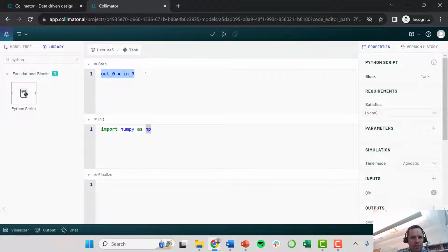I'm going to go ahead and delete this block, and here is where I'm going to start coding in my basic model. I'm going to start with this core material balance, which is a differential equation, and this is qin minus qout. So dV/dt equals qin minus qout. However, remember, qout is not something that's going to be directly defined. It's something that we're going to have to calculate. So I'm going to work backwards here a little bit.